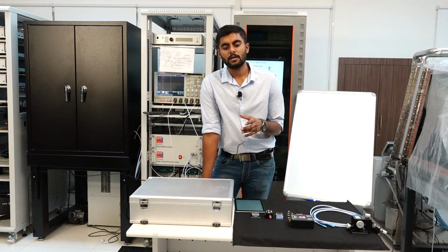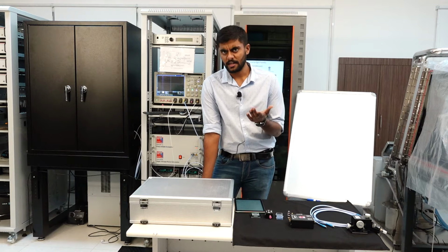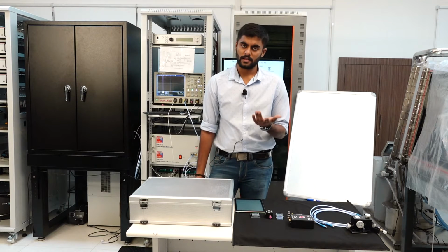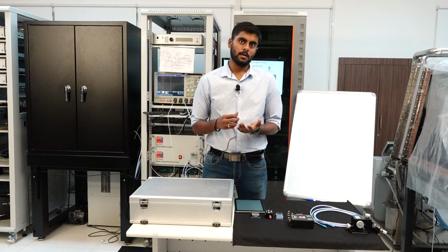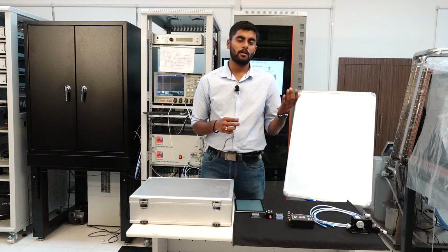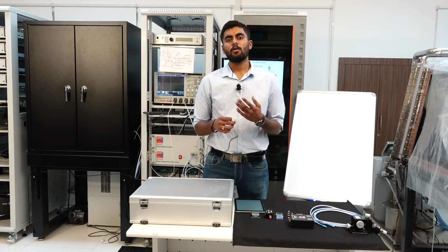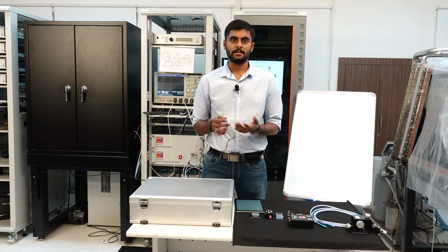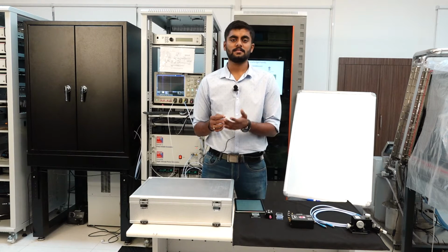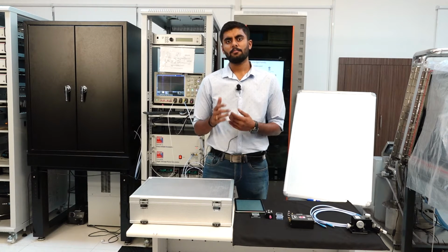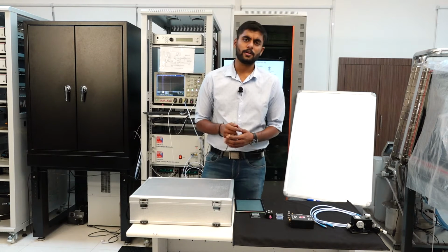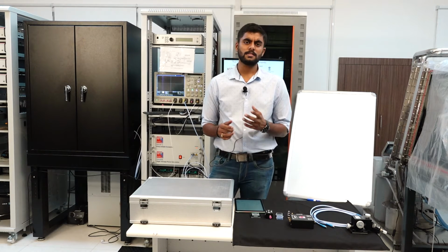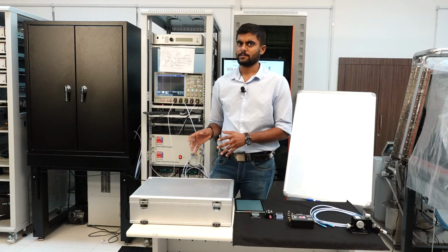You also need to understand that in a pulse characterization technique, as you can think, you will also need to do the calibration of a system. The calibration is important because whenever you involve any wires around, you also involve a lot of different parasitics. So these wires also then have capacitances, resistors, and everything, and they can then play around with your waveform if you don't calibrate the system well. And in this video today, we'll talk in some detail about the calibration of the TLP setup as well.